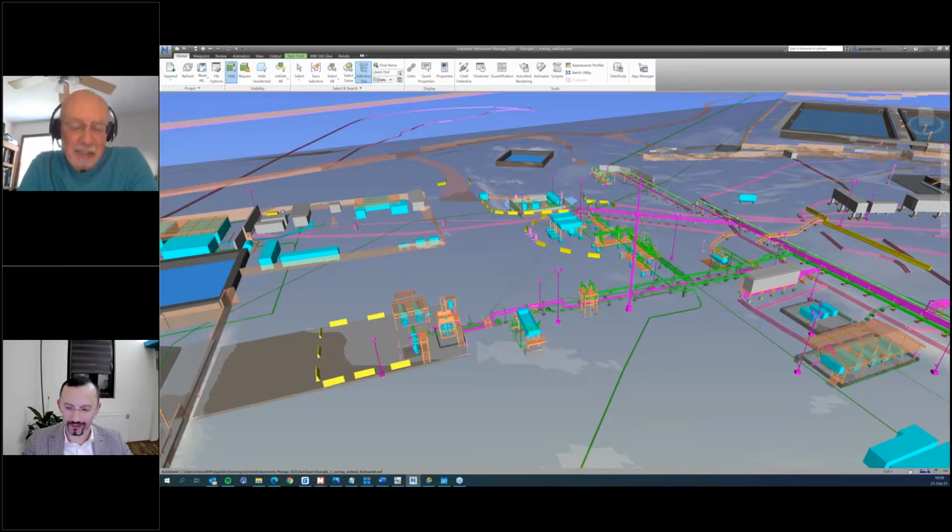Yeah. Anyway, one more last question before time is up. It says, have you used any other control besides targets, like total station? Yes, of course. We also had total station, and the company who did the laser scanning also made some total station survey in each location, and they made the registration, including those survey points.